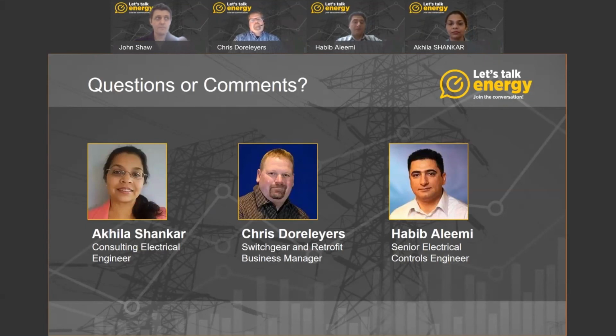If loads are sensitive to voltage and frequency dip, or there is a limitation, it is better to bring the diesel generator first online and then parallel the natural gas generator to the bus. The diesel gensets have higher power density and therefore would have a larger kilowatt rating than a natural gas genset for a given footprint.